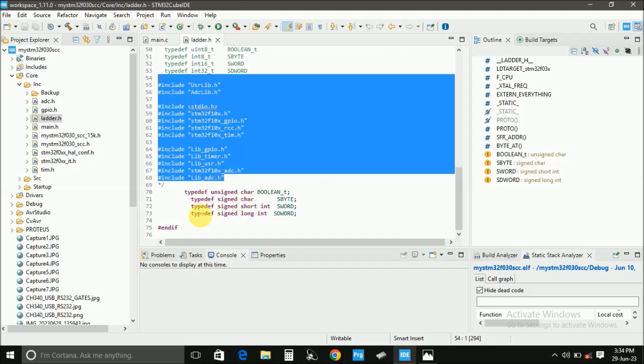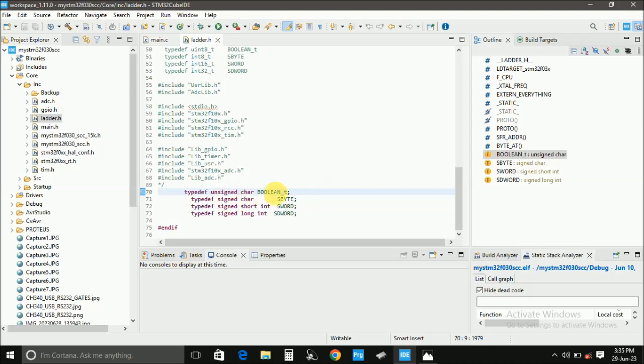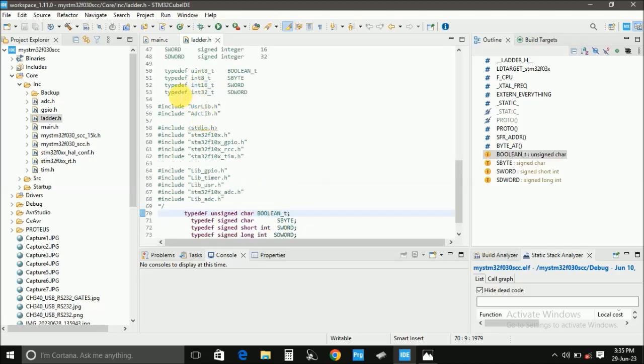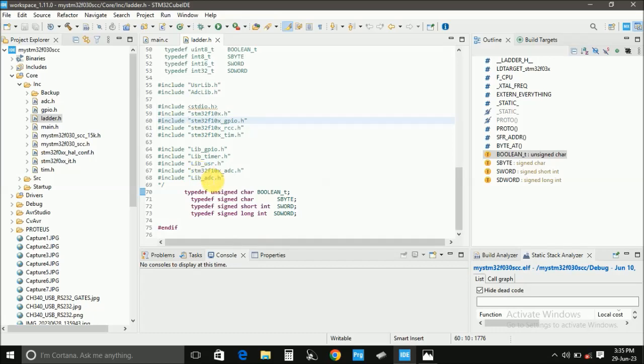And then also the tab definitions there, you have to change. You see the difference there. That is the adjustment that you have to make to the ladder file that ldmicro produces, right?